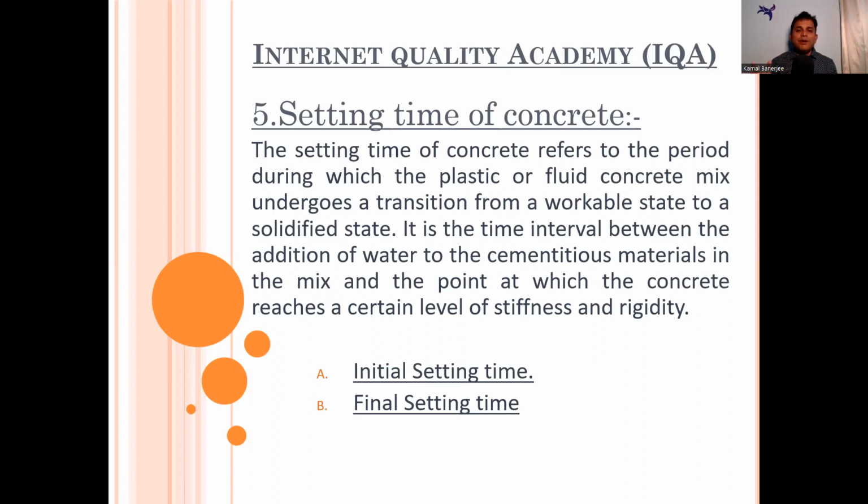It is the time interval between the addition of water to the cementitious materials in the mix and the point at which the concrete reaches a certain level of stiffness and rigidity. So from the time we add water, it starts reacting with the cement, and when the reaction stops, we get a solidified mass or solidified concrete. This total duration is called the setting time of concrete. And the setting time is divided into initial setting time and final setting time. What initial setting time and final setting time are, I will discuss in a separate video.